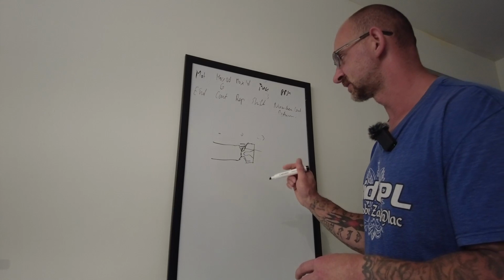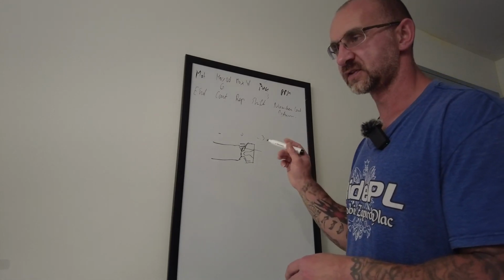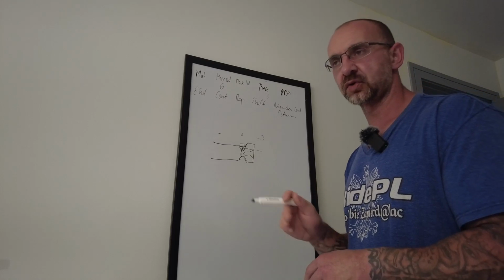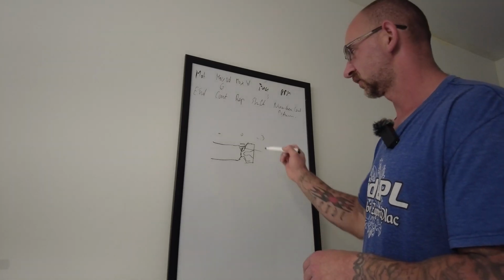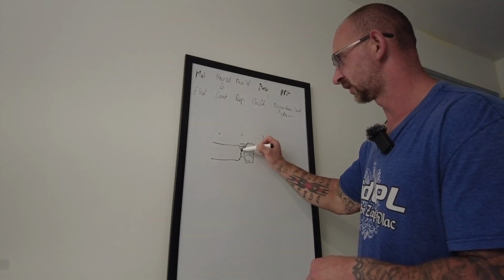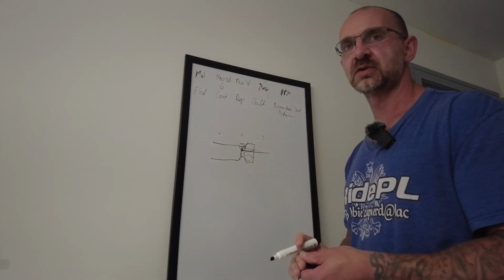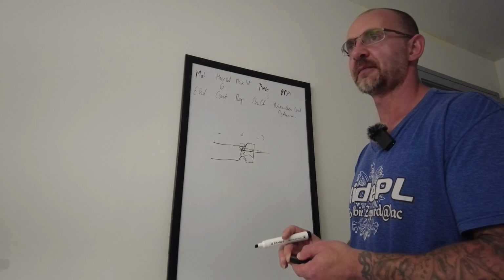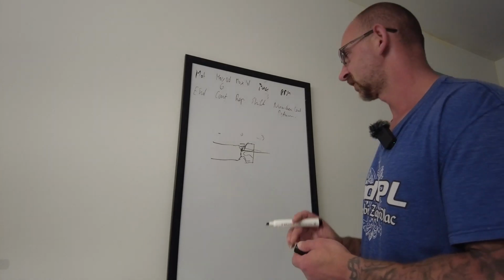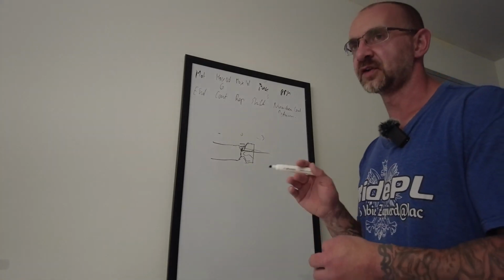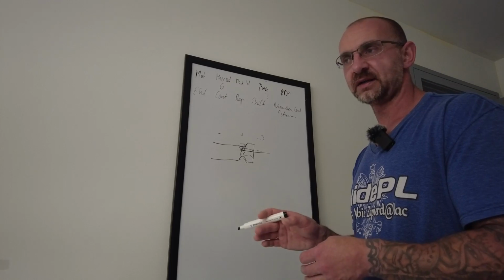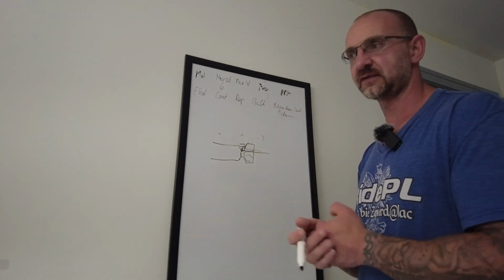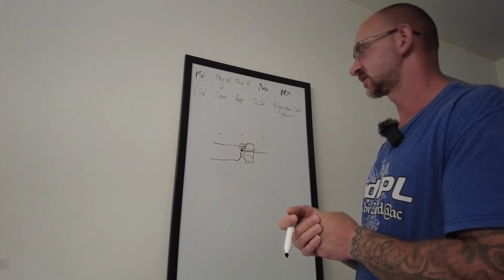I don't know why it does this, but be careful. When you work with stuff like that, go to toolpath or go to trace, and your machine's going to show you it's doing this here and it's cutting here. She will follow exactly what she does on a toolpath. There's no doubt about it. It's not a glitch. So don't run the machine, or if you're going to run it dry where it's not cutting the part, see how it's going to behave. If it's going to come out, you just save yourself a little crash, right? Or some destroyed material.